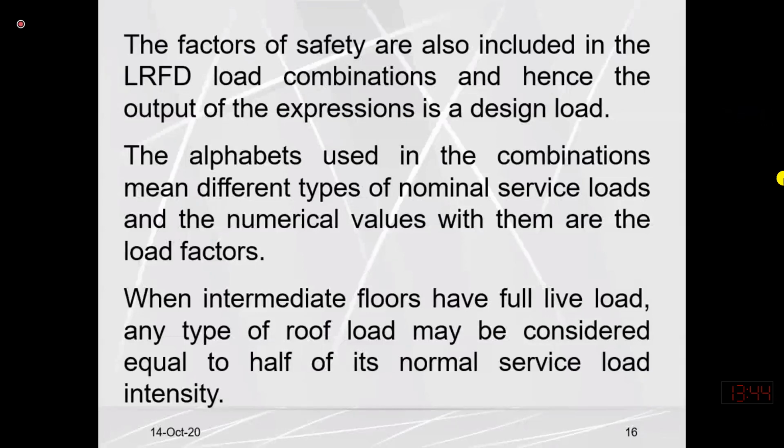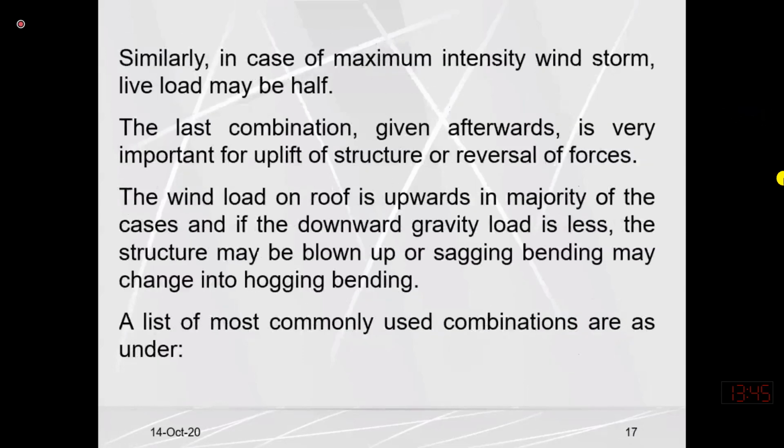Further, if I do not have roof access, then I can economize the beam structure and the other slab structure on the roof, because I don't need to design for the full live load. Similarly, in an institutional building, you are sitting in the classroom, maybe on the ground floor or on the first floor, so I must not consider a very heavy live load for the roof. So the roofing beam may be economical.